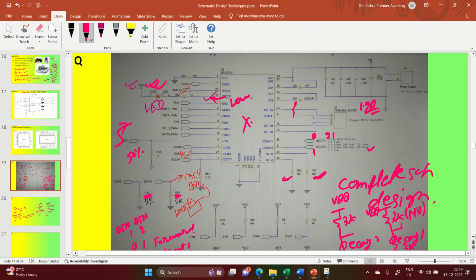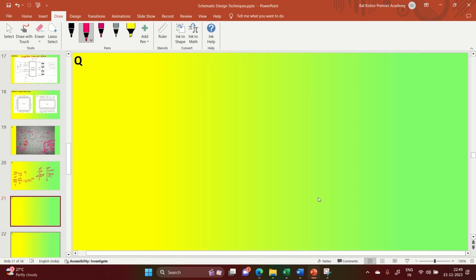At the same time, this particular pin you can take out. If you want to take that out, let's say this is my VDD, and this is my 4.7K, and this is my fault, and this is my MCU pin. Whenever the MCU pin sees it high, it will see no issue.